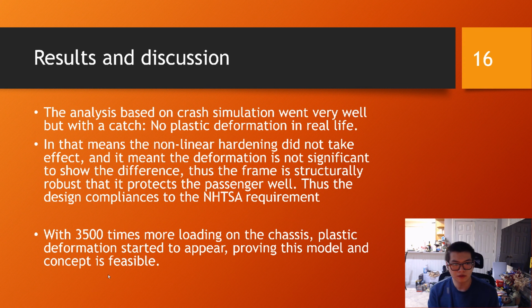So the result discussion. The analysis based on the crash simulation went very well, but there is a catch. As I mentioned, there's no plastic deformation in real life. And that means the nonlinear hardening and the nonlinear behavior of the steel haven't been shown.